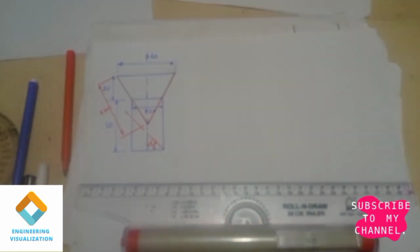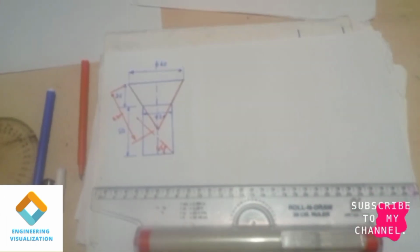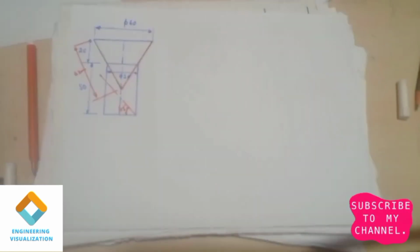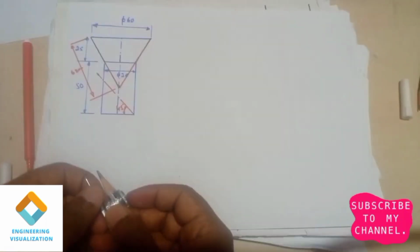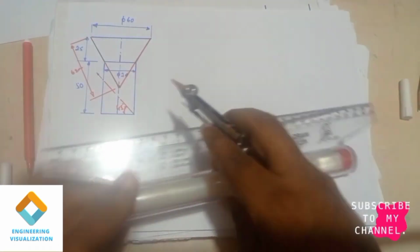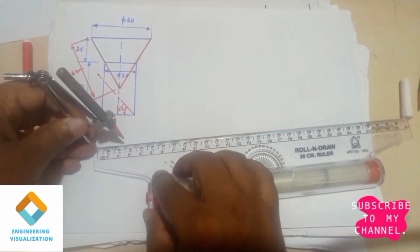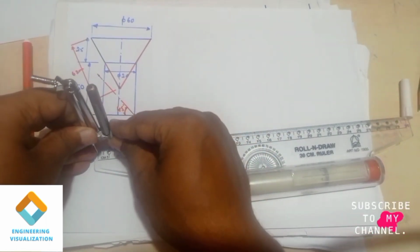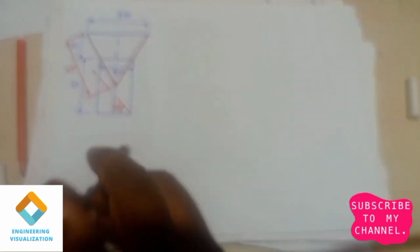So now we will be constructing the top view of the cylinder. Because in this problem the cylinder has been beveled, meaning cut, we will be constructing only the top view of the cylinder. So here the cylinder has a diameter of 30, so I'll be taking the compass. The radius will be 15 mm. 15 mm means 1.5 centimeter from the scale we need to measure. Okay, draw a circle.